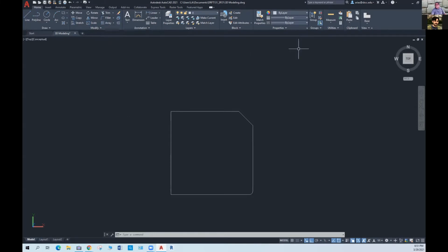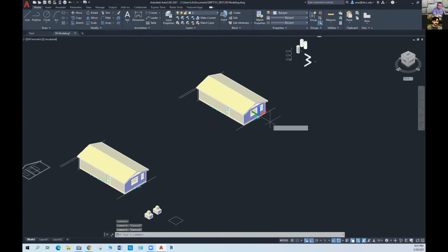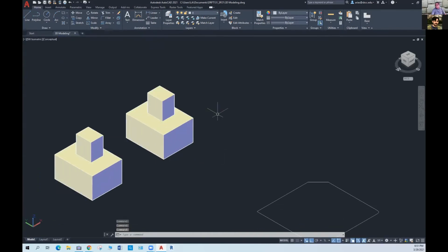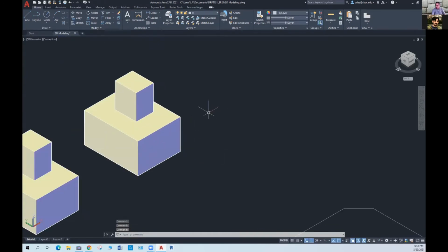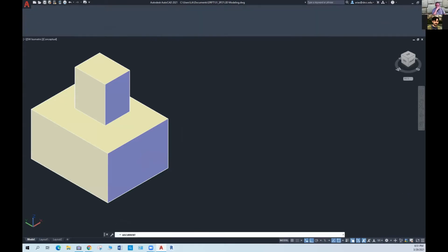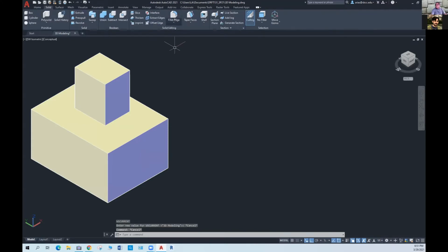Now in 3D, we have something similar, with the difference that it will create that kind of object for the whole edge of the plate. So let's go to 3D modeling, then to solid, and we see fillet edge and chamfer edge. These are the two tools I can use. Let's start with fillet edge.